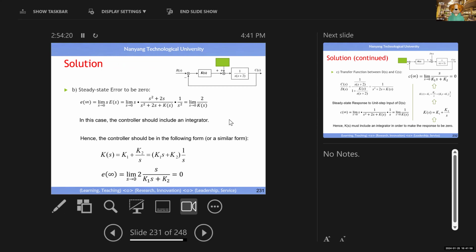Okay. Now I change my mind. Now you see the magic solution. Now I want the error to be 0. This helps you to know the magic power of the PID, right? Now you say I change my mind now, 10% is too big. I want the error to be 0. What will be the solution? There's no way if the K is a constant.